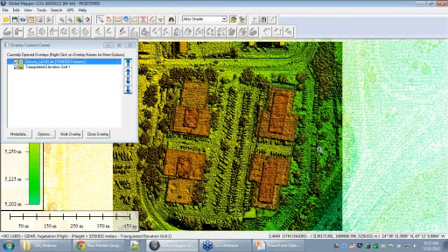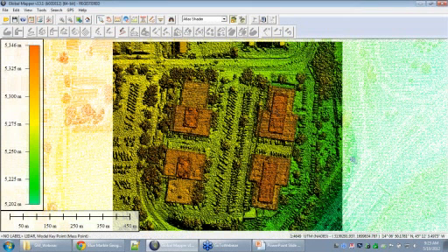And when we hit OK, it's going to start doing that triangulated surface. So that happened fairly quickly here because, again, I did focus on a fairly localized area. We could do this whole file without a whole lot of trouble. If you're working with very large, high-density clouds, it's going to take a few minutes to get through that, because it is actually a pretty rigorous analysis when you're dealing with millions and millions of points, as is common in a LiDAR point cloud.